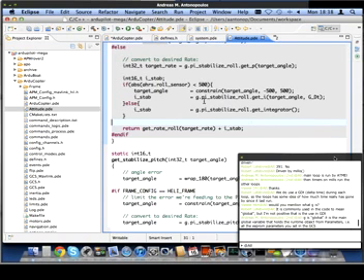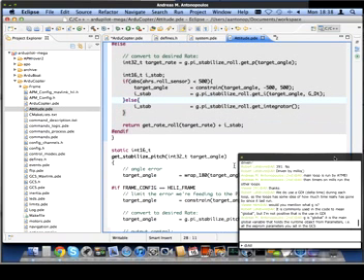So that's where we're taking the output from the stabilized angular controller and passing it into another controller, which is get_rate_roll. I don't think we need to go into that, but get_rate_roll is going to be another PID controller, which is going to take that desired rate and pass back a number, which we will then in turn pass back up to the main ArduCopter code.